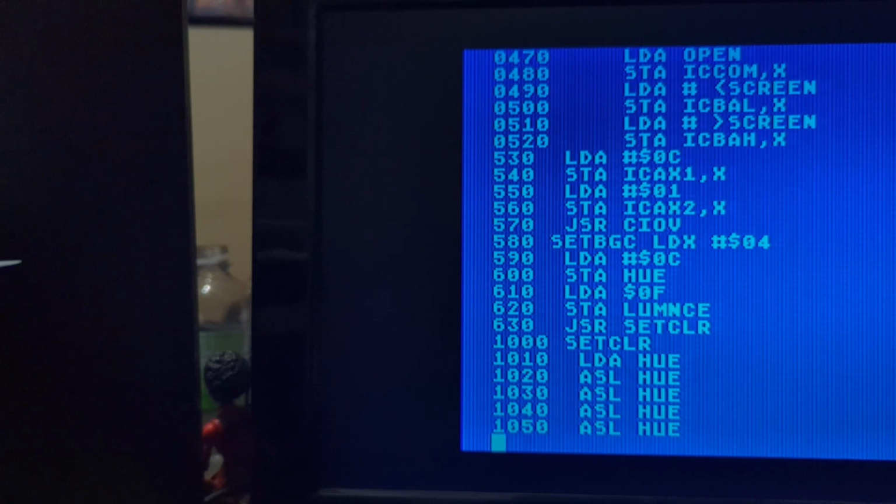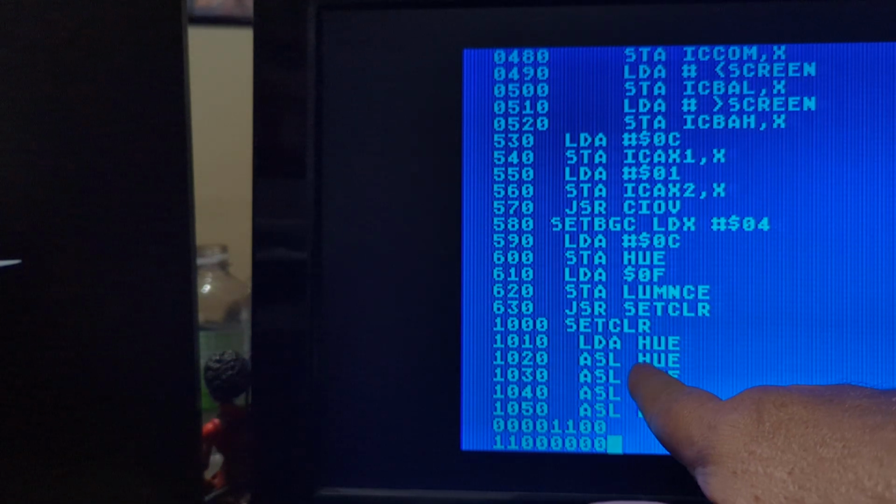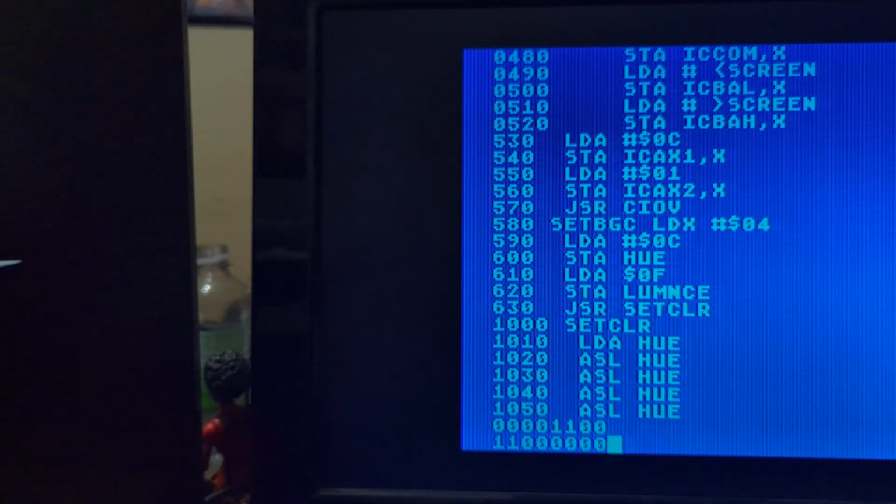So what that means is I started with this, and then after I shift the bits 4 places to the left, it looks like this now. Because remember, arithmetic shift left, as I go left, it puts zeros on the trailing end. So it doesn't rotate around like rotate left would. And even if it did, these are all zeros anyway. So that's what's going to be there afterwards.